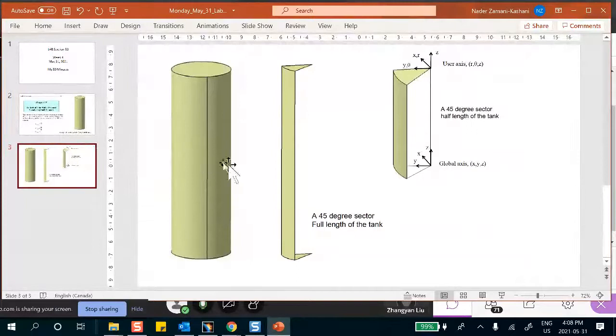Okay, I'll cut it halfway in the middle. But also, I need to take a slice only. And then, of course, you have to put symmetry restraints on these free edges that you create. Here is the thing that I've taken. In this particular problem, I've taken 45 degrees. Really doesn't matter. This is the thing that you're going to model. This is the thing that you're going to create geometrically, and then mesh it with shell elements, and then proceed. However,